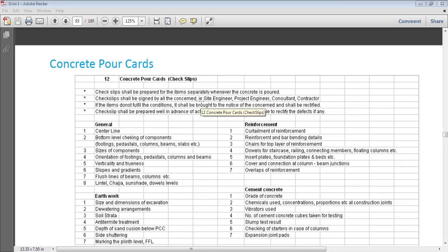At the same time, you are going to mark the lines. We call it the center line, or the excavation lines. That is our first step. If you see how they implement the plan, converting it into the field, they make small boxes where they are going to start the concrete or column work. At first, they make a square, or whatever the region or layout of that particular area.